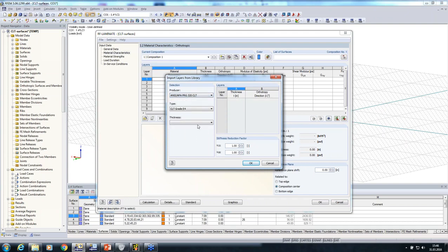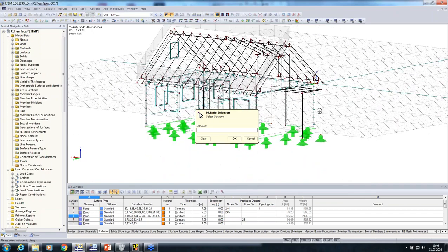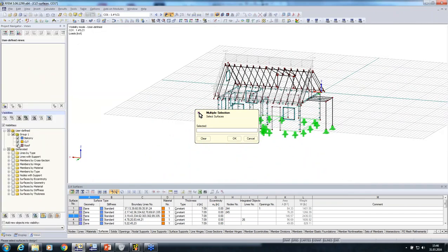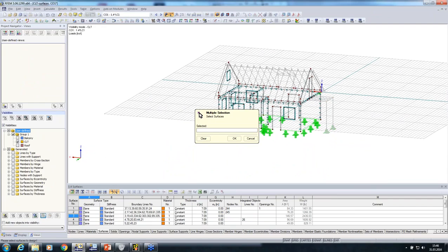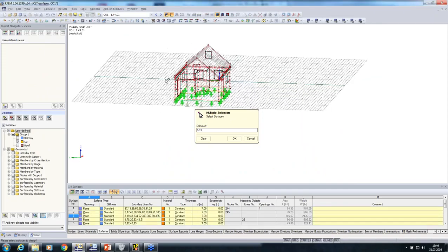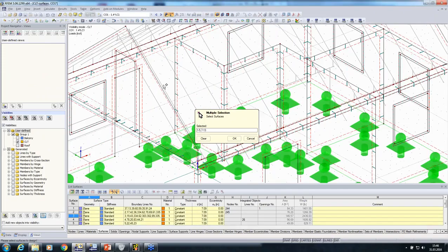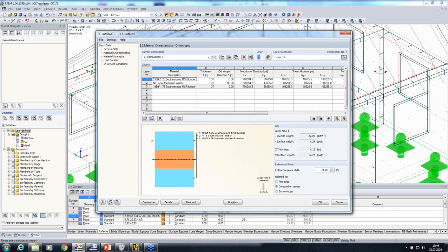So this one, and for the walls we're going to make a more slim plate, because there is not much loading I will expect from that. Say okay, now I'm choosing the walls, therefore I will switch off the roof and maybe the balcony, does not really matter, and now just choose all surfaces, and for the floor I want to have another setup.